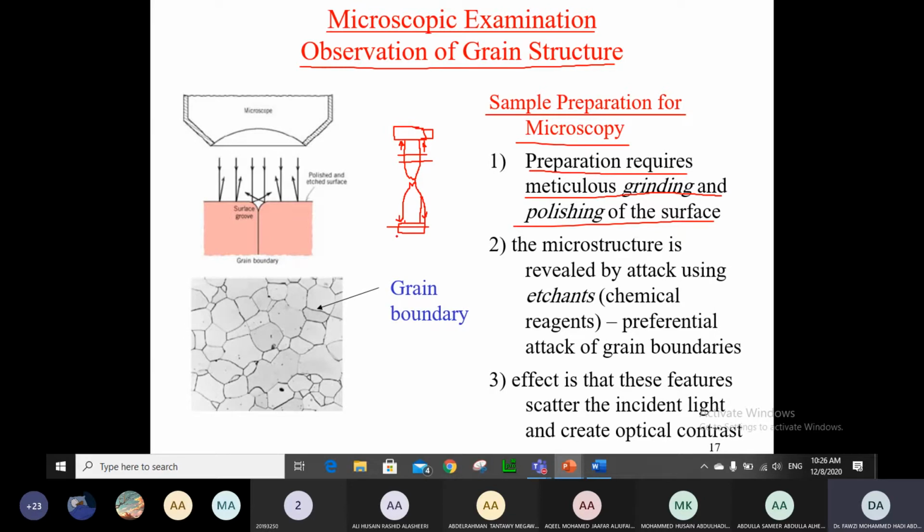So basically, we do the heat treatment of the specimen before we do the tensile testing, and once we do the tensile testing, then we cut from here to get that part, because this does not go through any plastic deformation. Plastic deformation causes the material grains to change. For example, if I'm cutting from here and it looks like that, if I'm cutting from here, it would look elongated, basically the grain. So it will not be giving you the original shape of the material.